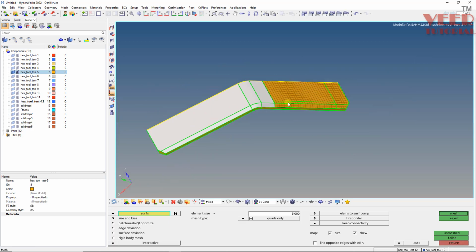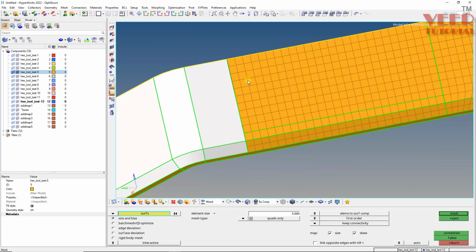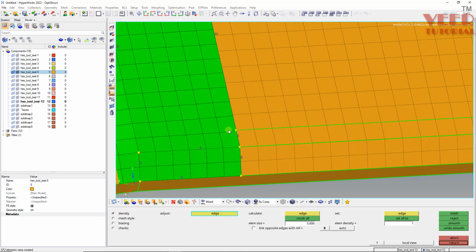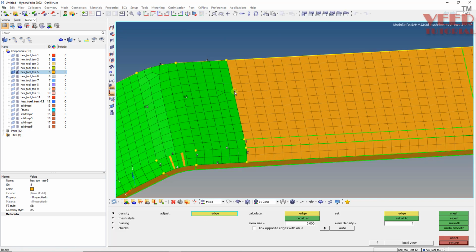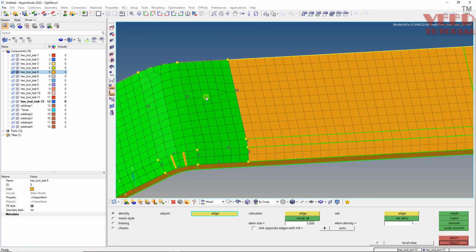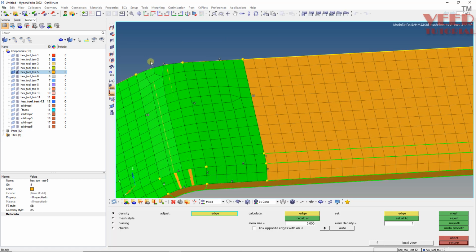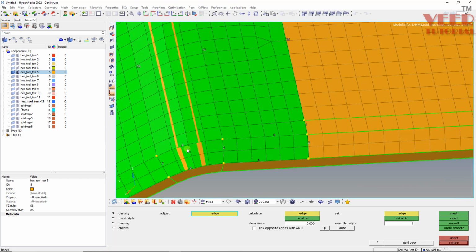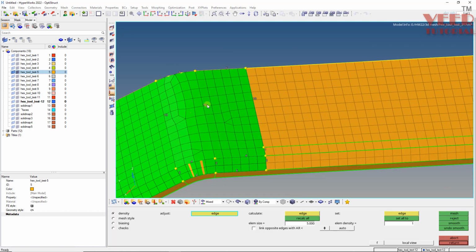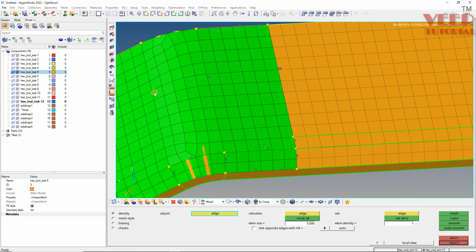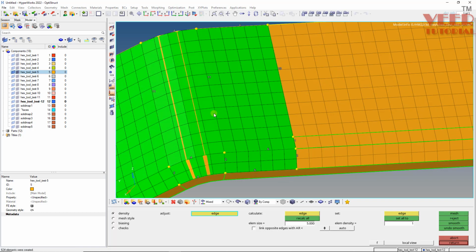So it is simple. In the remaining part we just have to make the connectivity here. So here 2, here 10. Okay, so here you can see 4 and make it also 4 here, and this is 10, not 10, this should be 11. So perfect quad here. Similarly here make it 11, perfect quad.